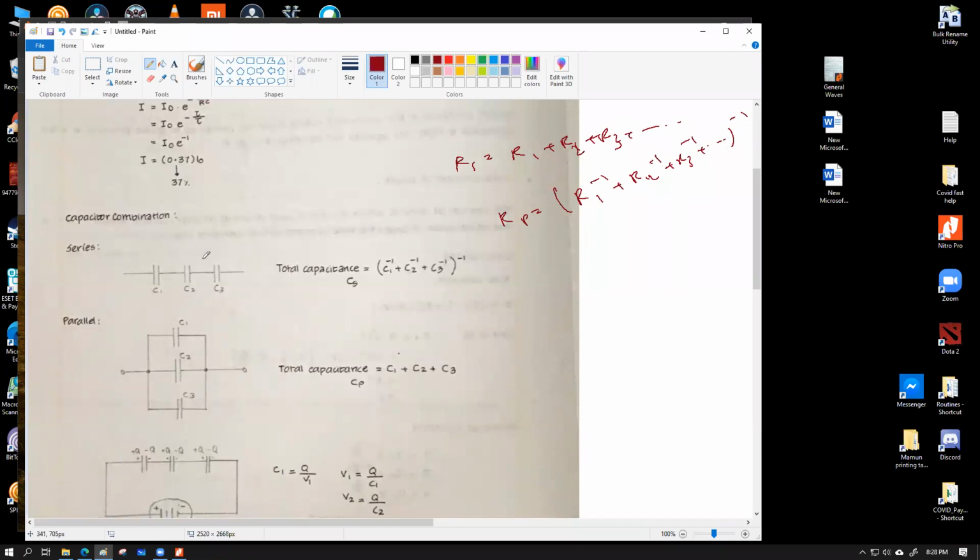Capacitance is just the opposite. Have a look. Total series capacitance is given by a formula similar to parallel resistance. So the formulas are actually changing shape. Whereas total capacitance for the parallel part will be calculated by the basic sum. Why does this happen? I'm coming to that; for now just take the information in. So this formula for series combination or parallel combination is exactly opposite compared to what happened for the resistor combination. That's one easier way to remember.